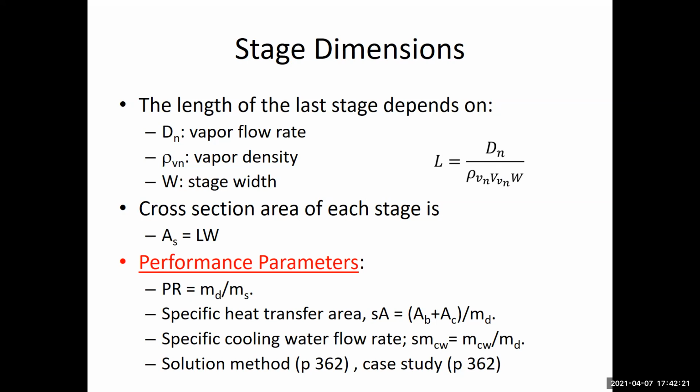The heat rejection section is the one that has some changes due to the difference in the flow rates. At the bottom, we have the brine, which is being decreased from one stage to the other, but at the top, inside the tubes, it is not M dot R, but it is M dot feed plus M dot cooling water.